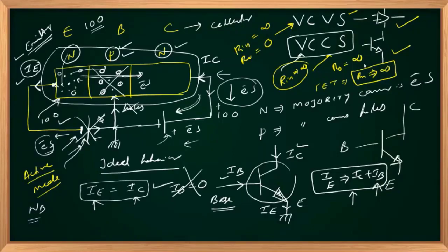There is no confusion in the case of MOSFET, but you will have a confusion in the case of BJT because in BJT we are having a base current IB. If base is your input terminal, you'll have a non-zero current and Rin need not be infinity always. So ideally it is not a voltage controlled current source, but IB is extremely small, normally in microamperes, so we can approximate your BJT also as a voltage controlled current source, or the other way, a source is required to control the operation of a bipolar junction transistor, right? Okay.